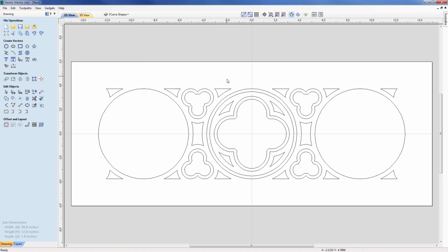Okay, so the next stage now is to make a copy to place it in the left and right circles. So I'm simply going to drag from the lower right hand corner and box pick all the way across, which should pick all the entities that I need. Okay, so we have all those selected, and I'm now going to click on them to put them into transform mode, and I'm going to hold the control key down on the keyboard and just pick that item up and just literally go down and place it on the center of the left circle.